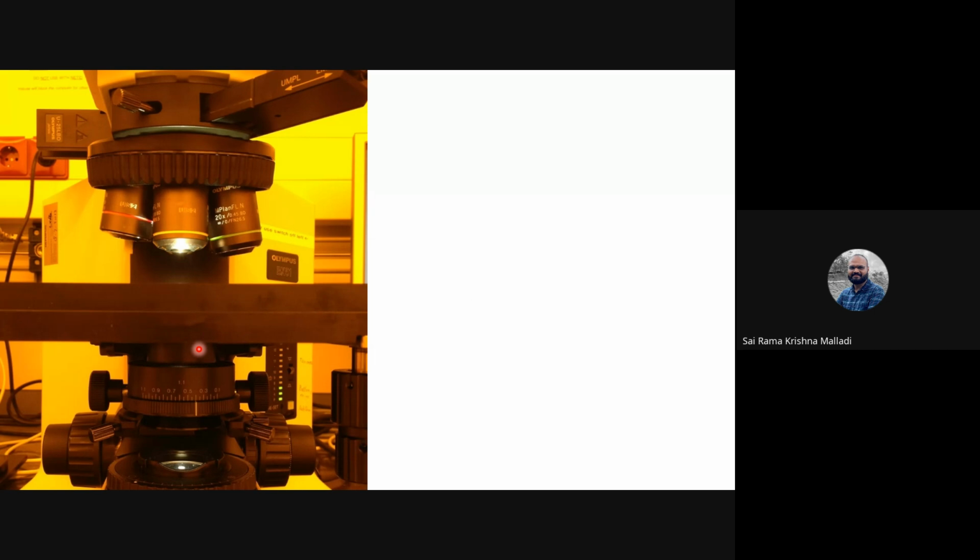So, with that background, this is how an optical microscope looks. This is an image from a metrological device inside a clean room. This is an upright compound microscope. It is run in transmission mode. The source is at the bottom. You put a sample on a glass slide and the light goes through, and you have an objective lens through which you reconstruct and capture the image on a camera.